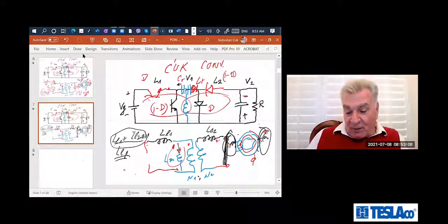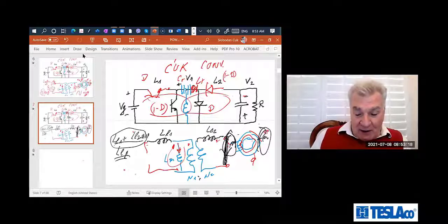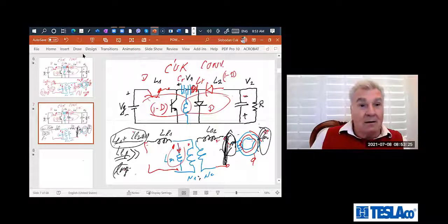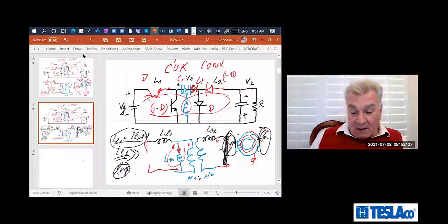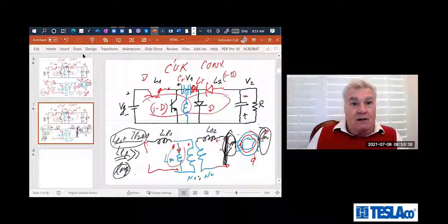What if this transformer is shorted? Why do they care how much of that is on the primary, how much on the secondary? They don't. They care that the total leakage inductance is large, right? Because when there is a sudden short, windings on a 60-Hz transformer get, for whatever reason, insulation cut off, and you get a short on the secondary.